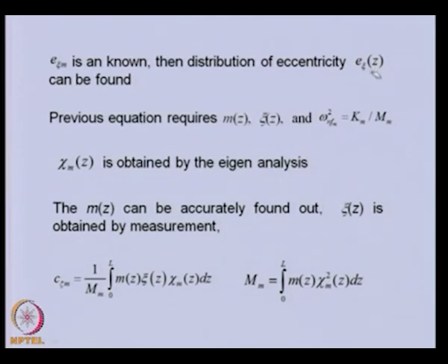If we know this, we can balance the rotor. So we outlined the basic method of modal balancing. Now we will use this particular method for balancing a simply supported rotor. In this case, we will try to balance the rotor for two modes, first by the first mode and then the second mode.